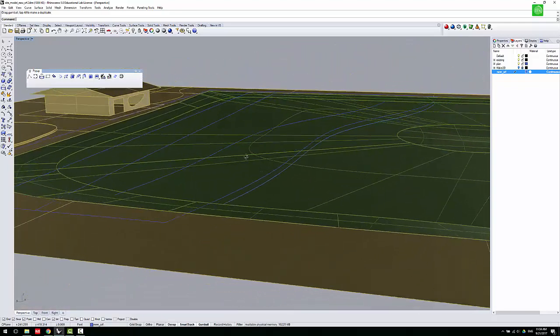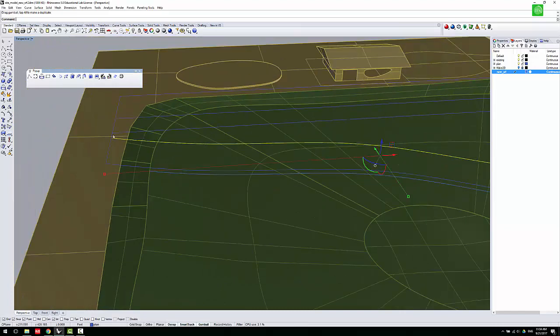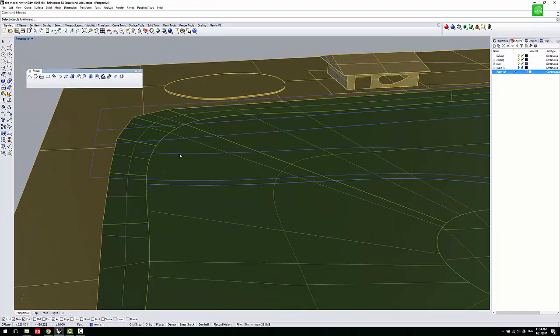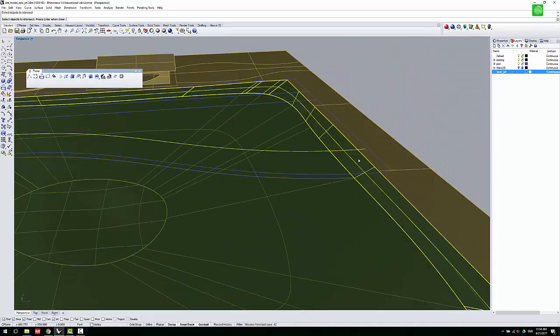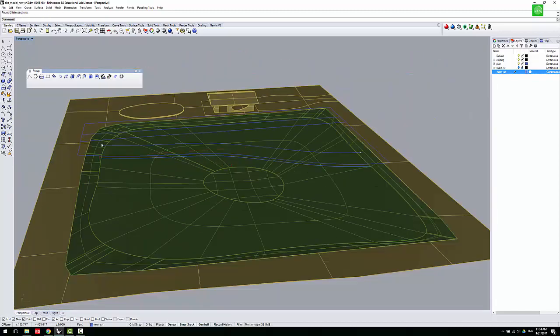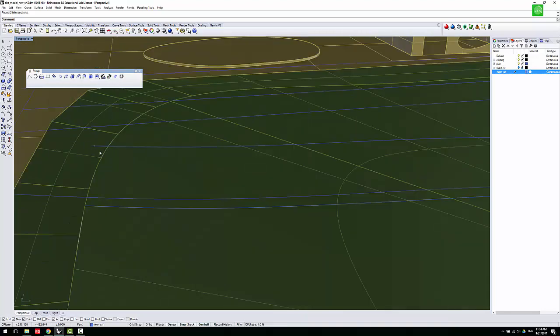It's really important to introduce a new tool called intersect. Select it and type intersect down there. Then you select this line, select the surface, and hit enter. This surface is the whole surface. Hit enter, and you will have 2 points. Those 2 points are really important. They are the places where the line and the surface intersect with each other.